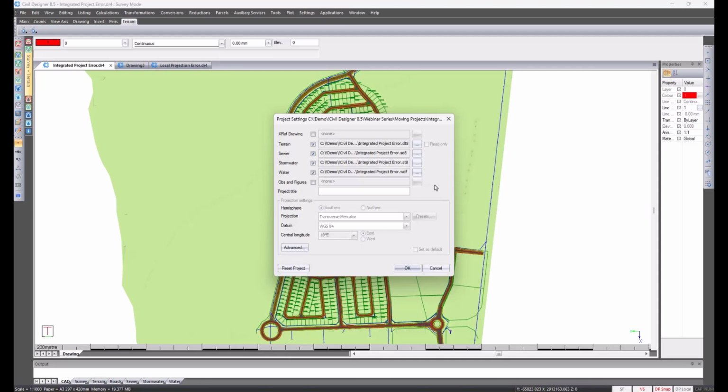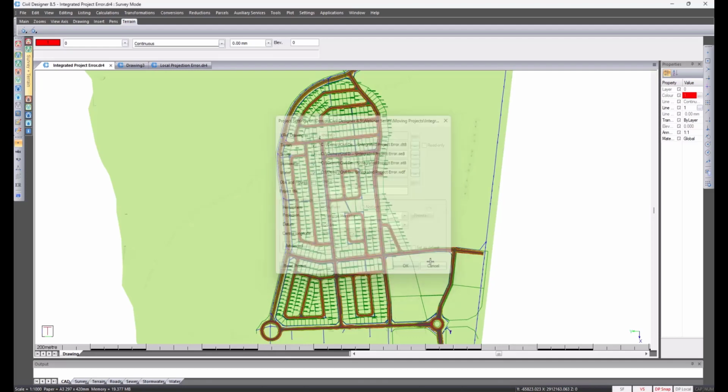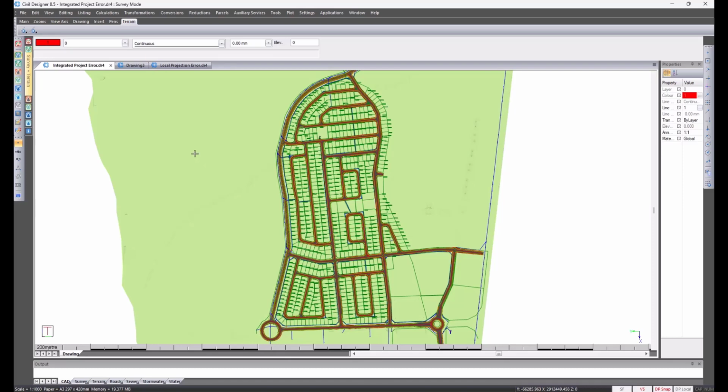So when you create the new project in the correct geo-reference position, you don't want to rename all your roads. This particular project has 35 roads. You don't want to go and change all the road names. So instead, what I suggest you do is rename the entire project. And then at a later stage, I'll delete the DTM file and put it in the correct place.